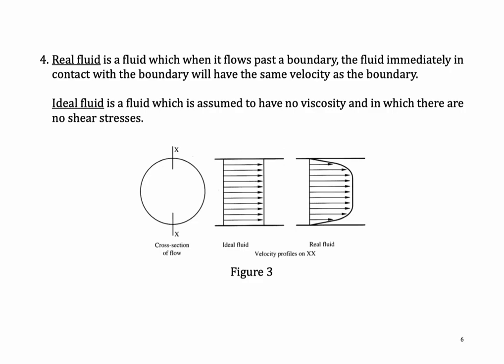In simulation, for example, it is difficult for us to add the effect of resistance. So sometimes in our calculation, we assume that our fluid is in ideal condition. In ideal condition, we call it an ideal fluid, which means it has no viscosity effect. No viscosity effect means the molecules do not stick on the surface.